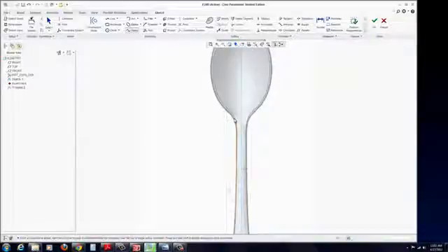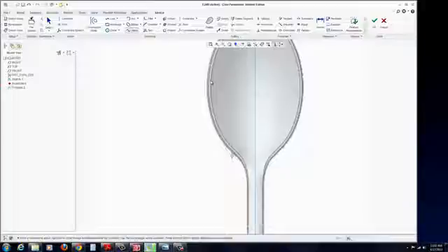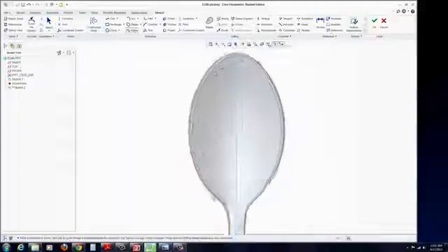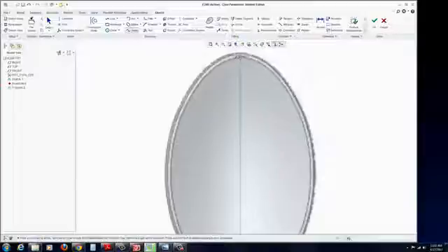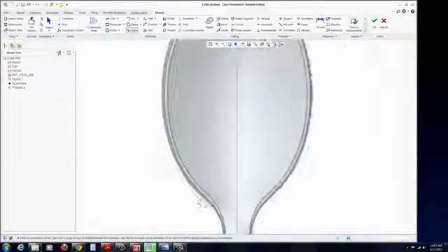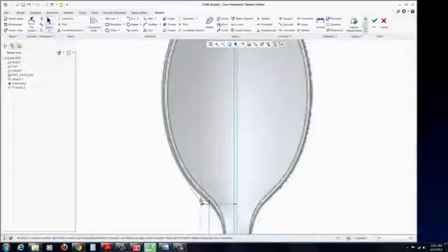And when you get to these edges here where there's a bend in it, you're going to have to put a lot more. If you accidentally snap to that center line, not a problem. I'll have to fix that in a moment. Now, when you get up here, stop before you get to the end. You want it a little bit of a distance away, and actually have it come out a little bit like this, because you're going to want to probably trim the end off because it comes off kind of strange. If you want to thicken it eventually, it might have some issues. That middle click. This one, the middle click a couple times. Get rid of that relationship there.